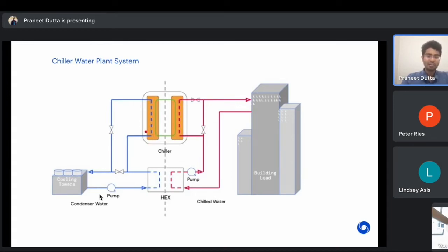And even if it was colder, let's say 40 degrees, it would obviously be able to do that more easily. In which case, you wouldn't need a chiller, you would use a heat exchanger. That's a separate concept. But the central way to think about what this does is it's able to make a colder medium colder by dumping the heat into a warmer medium. Does it make sense how the chiller works?